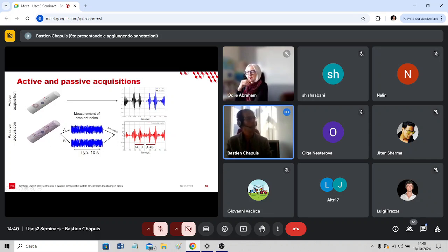And then we correlate these two signals. There are also other algorithms, but it works very well with correlation. We'll see some limitations, but we correlate these two signals, and by correlation, if we respect some hypotheses, we obtain this type of signals that are very similar to the previous one. So we have in positive time of our intercorrelation the propagation between A and B, and in negative time the propagation between B and A. And you can see that you can identify almost the same wave packet.